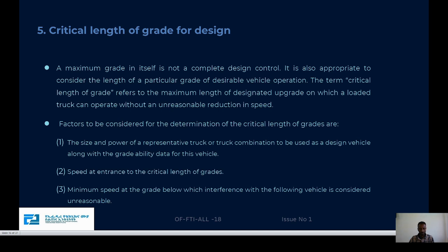The factors to be considered for determining the critical length of grade are, first, the size and power of representative trucks or truck combinations used as design vehicles; second, the speeds at entrance to the critical length of grade; and lastly, the minimum speed on the grades.